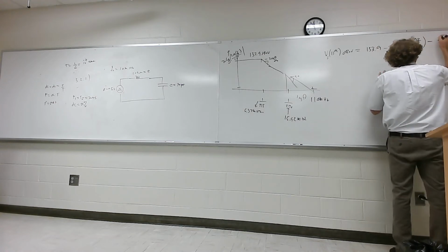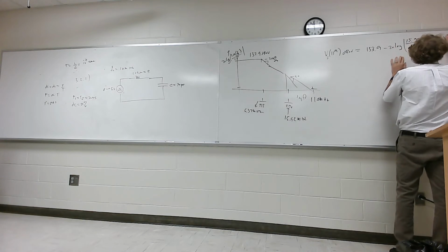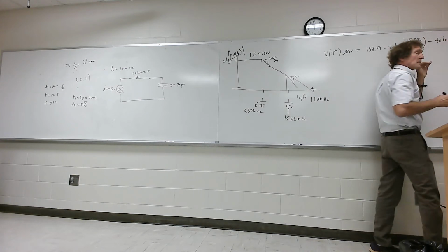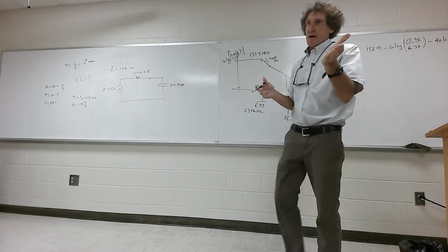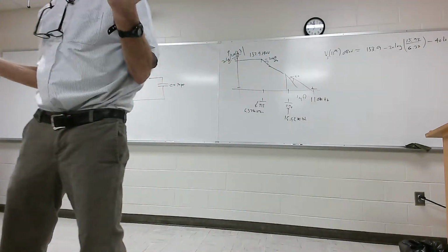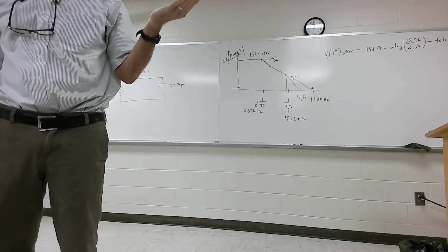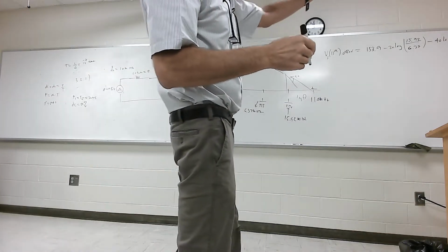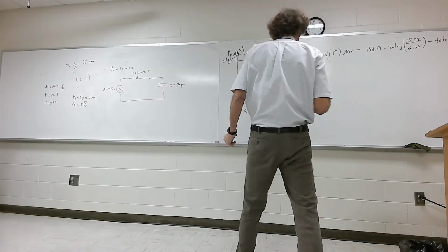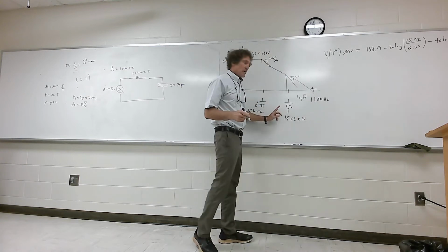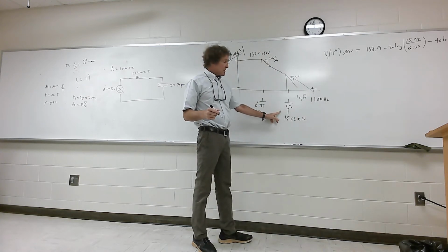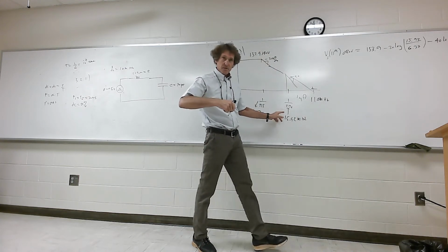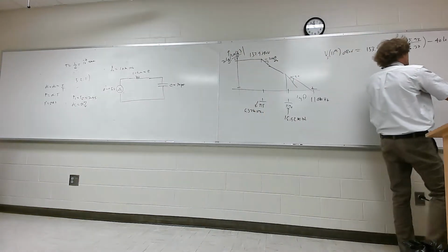Then I have to go down and do the 40 times the log of the upper, because now it's dropping at 40 dB per decade. If it was over just one decade, it would be 40 dB. 2 decades, 80 dB. Right? If it's not a decade exactly, then you have to take the ratio of the upper versus the lower frequency. Here, I start right here, where I left off. That's 15.92. That's my lower frequency, so I divide it through.